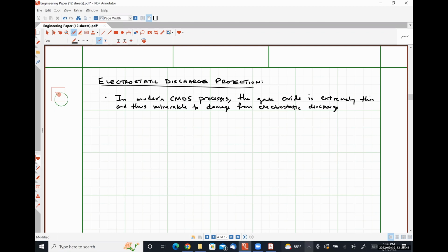If you buy any type of modern computer memory, video cards even, if it has any type of sensitive electronics, it's coming with some sort of electrostatic discharge protection, like it's coming in a bag effectively to make sure that static electricity doesn't damage it in transit. And then there are also structures in place within the integrated circuit. These structures are diodes. That's it. Simple diodes to prevent current from going the wrong direction and blowing stuff out, okay?